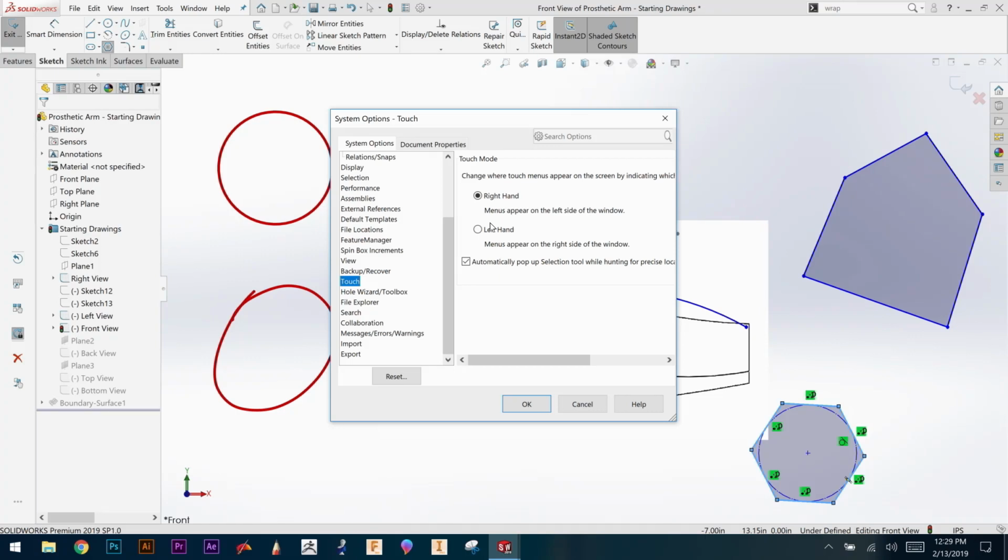Your workflow for creating the 3D sketch: you started normal to one of the regular planes, followed the sketch, then switched to another view and dragged your sketch to follow that curve. Right. I've seen another workflow: 2D sketch on a plane, create a different 2D sketch on an orthogonal plane, and then use projected curves to create that 3D curve in space. I don't know if you thought there were pros and cons of that, or why you did it that way. I guess you have less stuff in the feature tree.